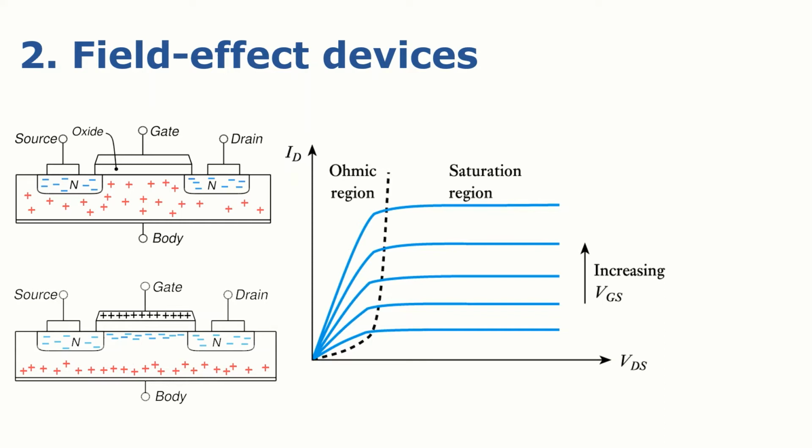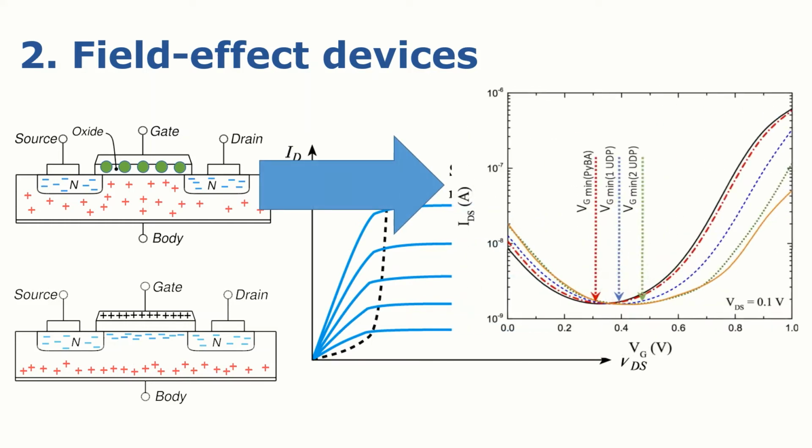On a field effect-based sensor, we look for current modulation through the absorption of molecules on the channel of the device, having a similar effect to that of a gate voltage, so that different concentrations yield differentiable changes in the electronic properties of the device, as we see on the figure to the right. By doing so, it is possible to detect and measure target molecules with very high precision and sensitivity.